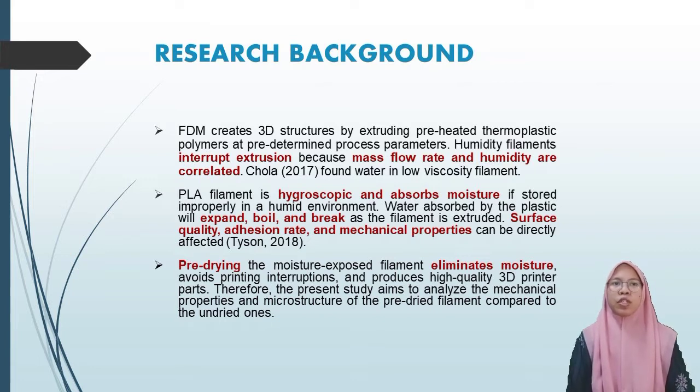PLA filaments are known for their hygroscopic characteristic, which is to absorb moisture. The filaments that have absorbed water will expand, boil and break as the filaments are extruded. This can affect the surface quality, adhesion rate, and mechanical properties of 3D printed parts. By pre-drying the moisture-exposed filaments, the moisture is eliminated, which avoids printing interruption as well as produces high quality 3D printed parts.